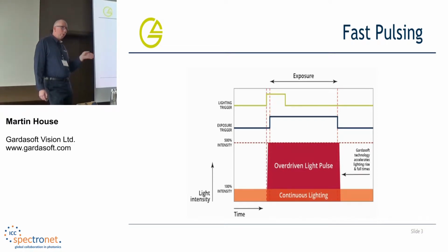The rise time is from when you give the trigger to your LED to when you're at full illumination. Now, if that edge is quite slow, you might actually be moving into your camera exposure time. So you could end up with almost a truncated type of illumination, so you have quite limited illumination during your camera exposure.